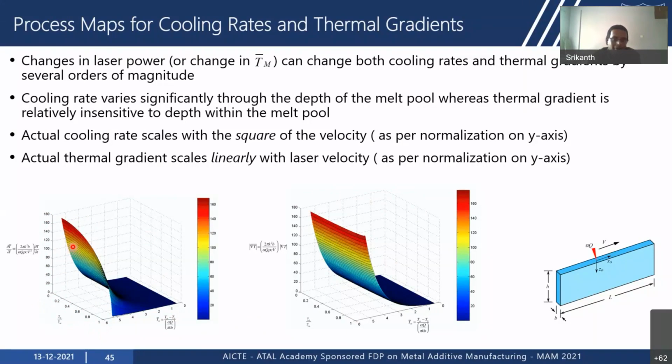You can see that both cooling rates and thermal gradients change by several orders of magnitude with changes in laser power and scan speed. And this is more clearly seen when you plot them on a log scale. But cooling rate is more sensitive to depth when compared to thermal gradient.